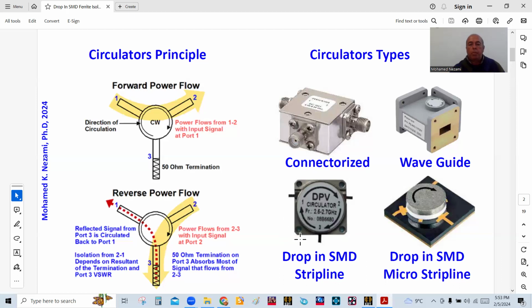But a stripline is basically where it comes in a metal housing. The top and bottom magnets are embedded in here, and then the three brass slabs usually stick out. These are the strip lines. And then of course you've got 4 mounting screws in here.